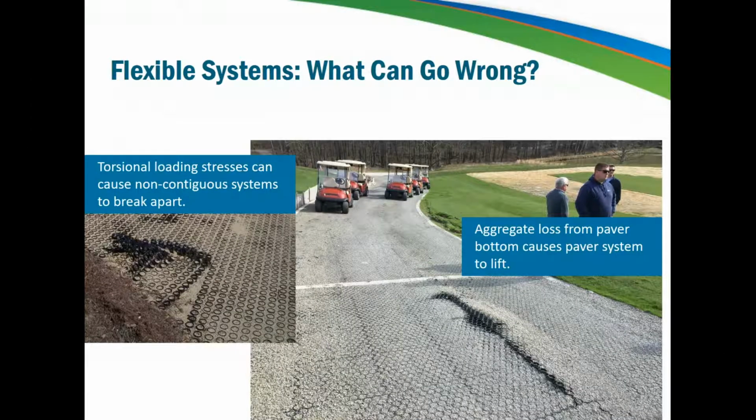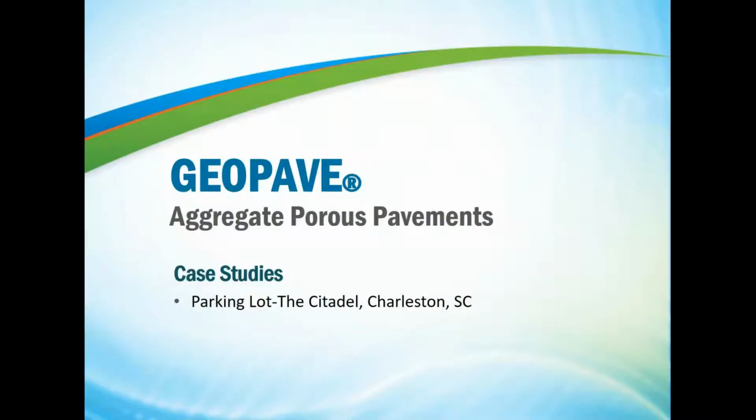And unlike the GeoPave units, which are rigid, there are flexible paver systems on the market that have some problems due to not having those shared common cell walls, or by allowing the stone infill to get underneath the system, causing uplift. Both of these issues are addressed with the design of the GeoPave system, with its rigid walls and that integrated mesh bottom we discussed. So just be aware that because the system says it allows stormwater infiltration, it doesn't mean it's going to be appropriate for your project site.